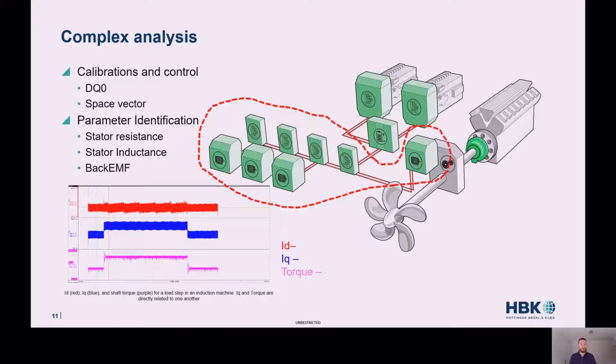This method is simple at first sight, but it has disadvantages. If the motor is wound to get non-sinusoidal back EMF voltages, then the calculated magnet flux is not correct since it must correspond only to the fundamental components. If the speed is not constant, either by a non-ideal speed regulation or eccentricity of the rotor shaft, the voltages will also fluctuate and influence the calculation.